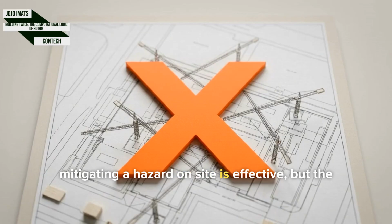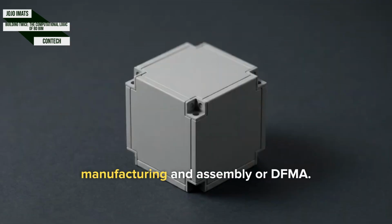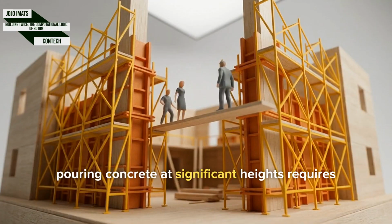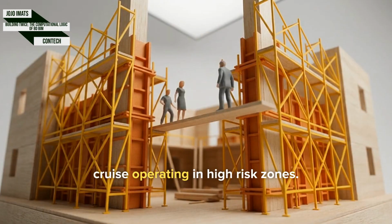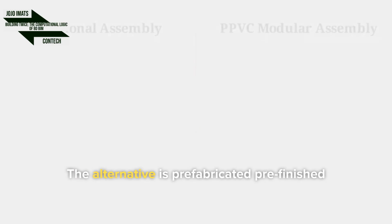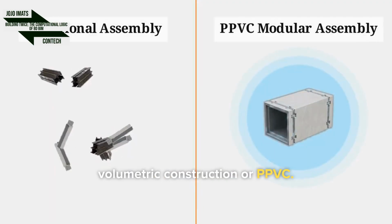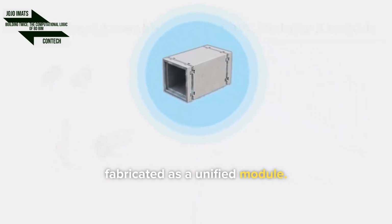Mitigating a hazard on site is effective, but the primary principle of VDC is to remove the risk entirely. This is achieved through Design for Manufacturing and Assembly, or DFMA. Traditional construction relies heavily on raw materials being assembled in place. Pouring concrete at significant heights requires complex formwork, extensive scaffolding, and crews operating in high-risk zones. The alternative is prefabricated, pre-finished volumetric construction, or PPVC. Instead of hoisting loose rebar, the structure is fabricated as a unified module.